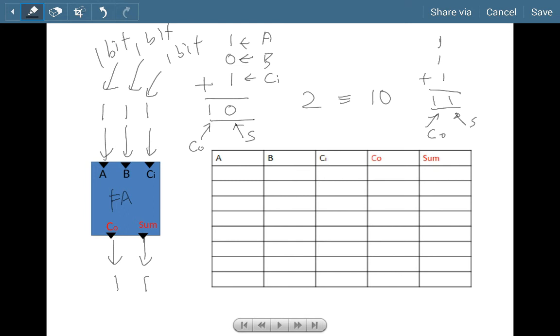Later we'll show you how you can use a FullAdder to add 2 binary numbers, and these binary numbers could be more than 1 bit in size. But first, let's fill up all the input conditions, all the possible ways to add three binary numbers together, each being 1 bit in size. So let's fill up the inputs of the truth table. I hope you still remember, the first rightmost column of the input condition, fill it up with alternating zeros and ones.